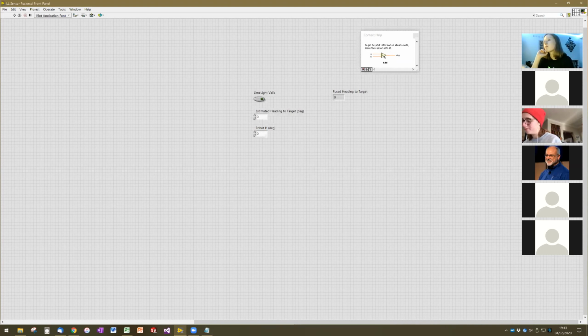So it can use the gyroscopes for these very fine changes and then use the compass to know that the robot's not actually moving, and remove that drift. One of the problems that we ran into this year is that at Bilo Largo, we can't use the compass. The building is a steel-walled building, and so it screws with the compass, so we had to turn the compass off. And so that's why we do still get some gyroscope drift.